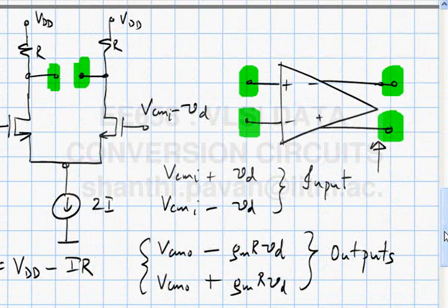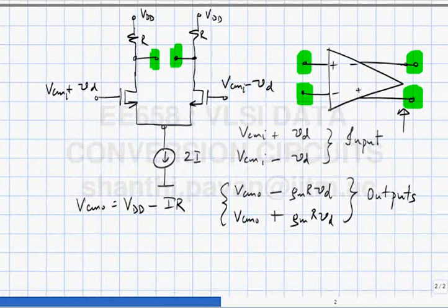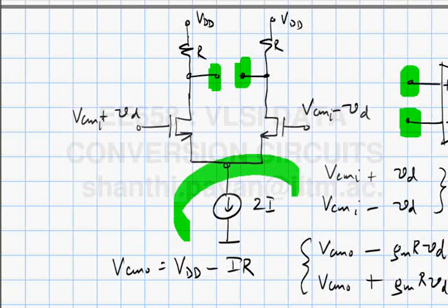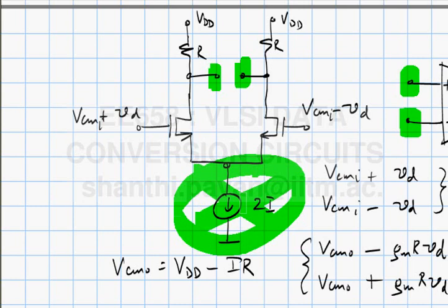the gain you can get from such an op amp is very modest. You make R very large. This is the same discussion we had with respect to active loads. If you remember, if you wanted a fixed current, you want to keep this fixed, and the size of these transistors fixed. If you want a large gain, the only thing you can do is go on increasing R. If I go on increasing R, what will happen? The drain potentials will keep going lower and lower, and eventually it will push the transistor into triode.